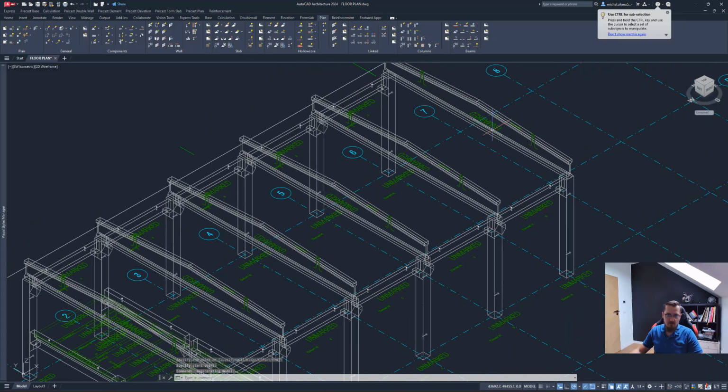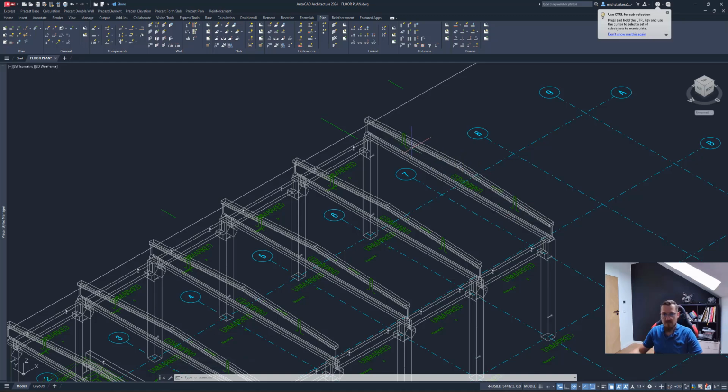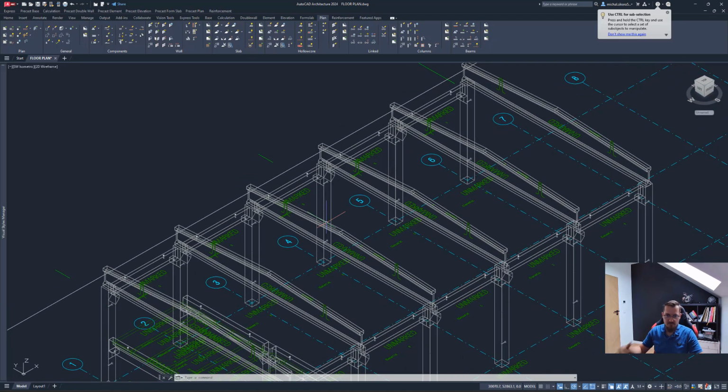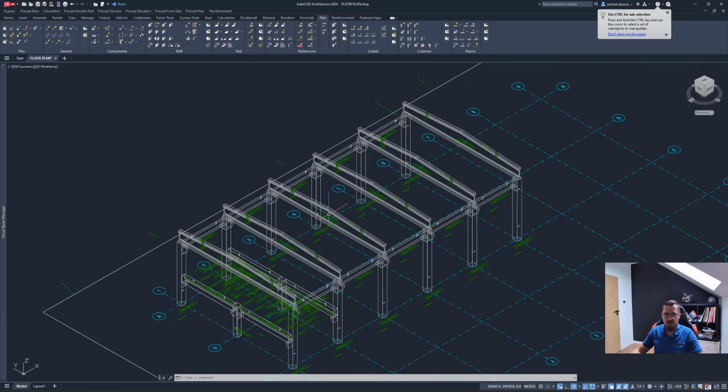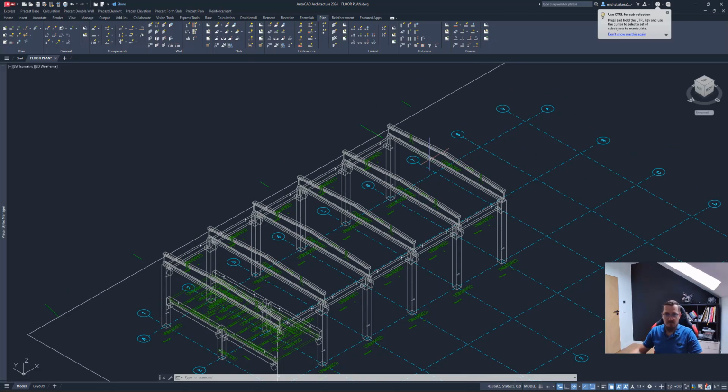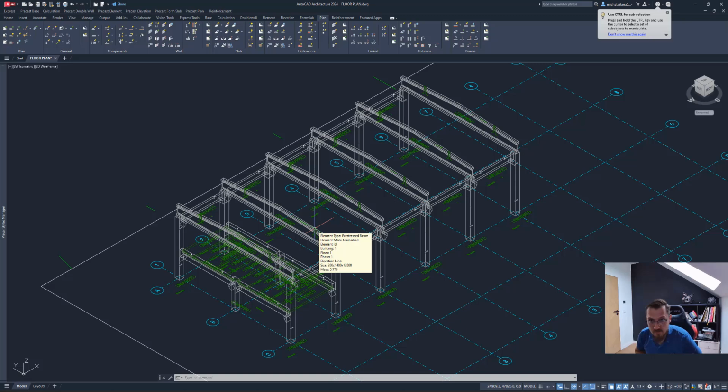And as you can see, we have now sloped columns, sloped beams, sloped pre-stressed beams. Basically, the software automatically recognizes that it's a sloped section, and it tries to create the slope symmetrically along the center of the element. And of course, the element can be as long as you need it to be. Of course, there are limits in the standard, for example, some element can't weigh more than X amount of tons, or be longer than X amount of meters. And logistically, some elements can't be infinitely long either. So we do have some safety precautions in the software to tell you if the element's too big. Basically, it highlights everything red. That means no good. And yeah, that's it. So this would be about it, about the modeling of all this.